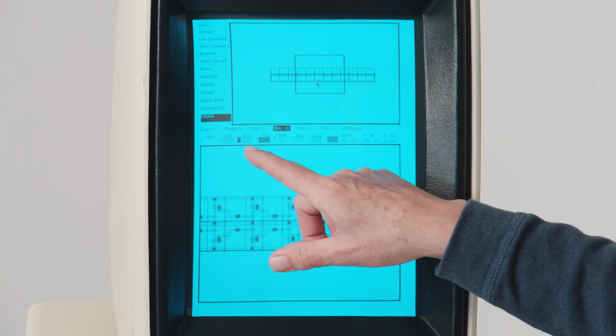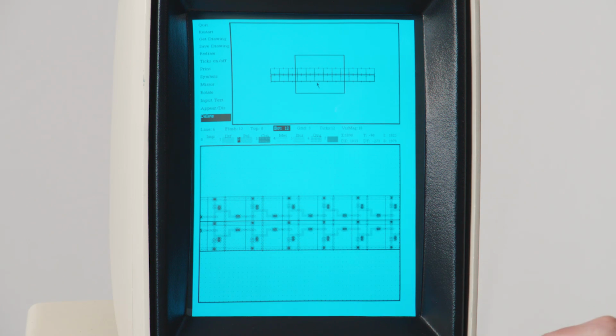So in each of these layers, for example, if I select the polysilicon layer here, it tells me that for this set of design rules it's 6 microns wide, and the flash, or the square that goes around a contact, is 12 microns on a side.